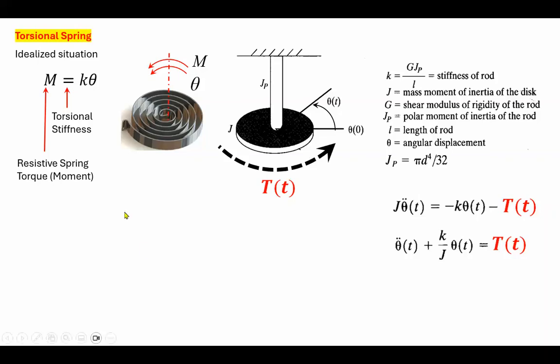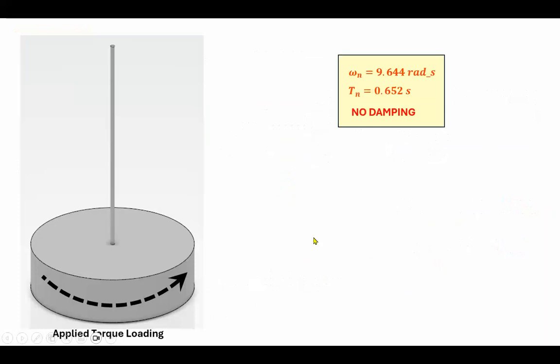Now, what we're going to do is model this shaft as a torsional spring, and the stiffness of that spring, based on the material property and the dimensions, is given in most strength of materials books, and it's given here. If you're interested in free vibration, then the natural frequency is the square root of k over J. It's right there, and that's what we did in 15.